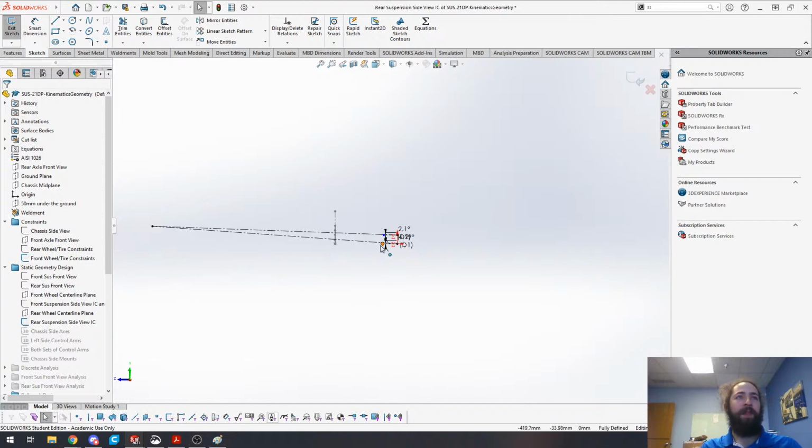Basically, the short way of explaining it is, anti-squat is the amount of force that is absorbed by the control arm itself rather than the spring under squat loads. That's accelerating, the weight transfer to the rear. How much of that is actually going into the spring damper system versus how much is the control arm actually taking, or both of the control arms, upper and lower.